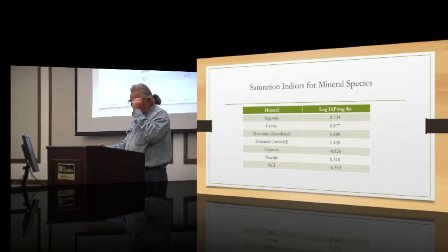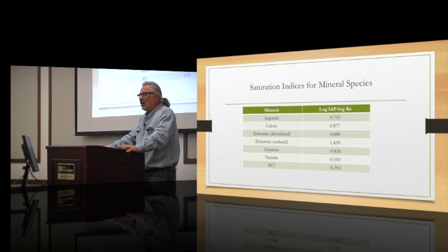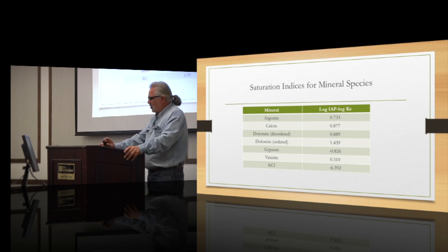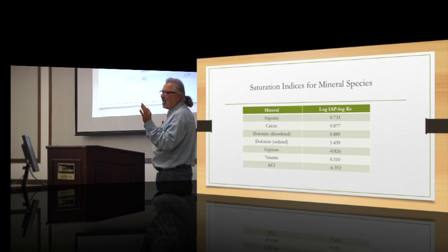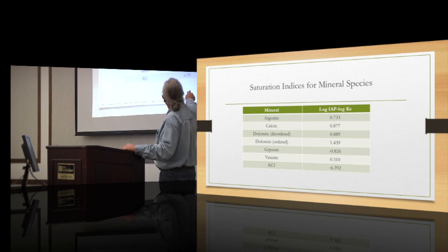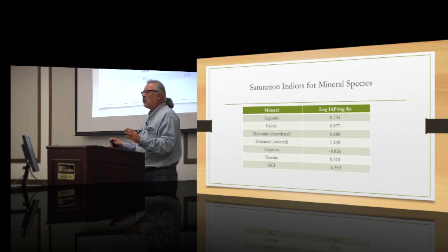There's one other thing that comes up, though. As I calculated the cations and anions, I went in and did some speciation work. And what it suggests is we're supersaturated with several insoluble minerals in the soil: aragonite, calcite, dolomite, vaterite. We're supersaturated with respect to those minerals.